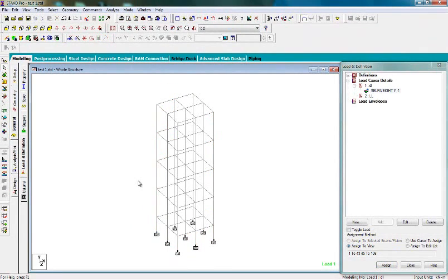Because self weight will be coming to everybody. Fine. So after the self weight there will be some loads like the loads of the wall coming all over the beams. Those are also dead loads: the loads of the wall coming over it, the finishing, the floor, the slab. These are all also dead load. We haven't added the slabs and all till now. So for that what you need to do is DL, dead load only.